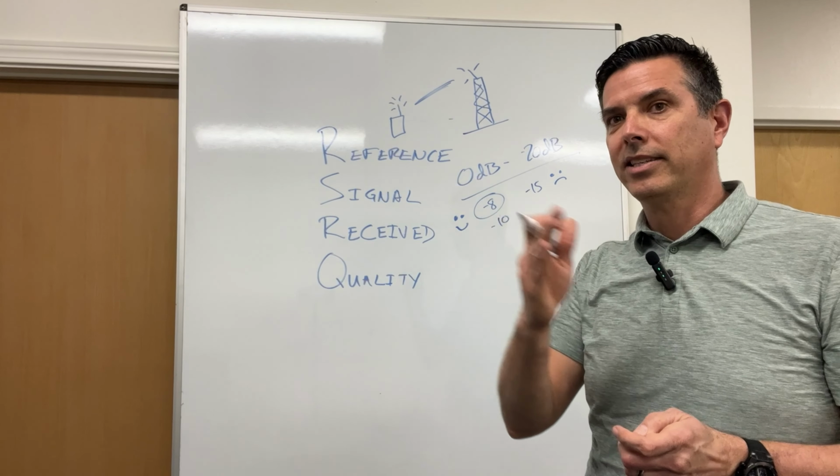Drive testing is what the operators do for their macro sites to measure their footprint and confirm that it's built right and it's plumbed right. That's drive testing. In a building, you do walk testing. You usually carry a scanning receiver or some other type of measuring device. And when you're walking through the building, you have to physically stop every 5 feet or so and touch the map to tell the system where you're at.